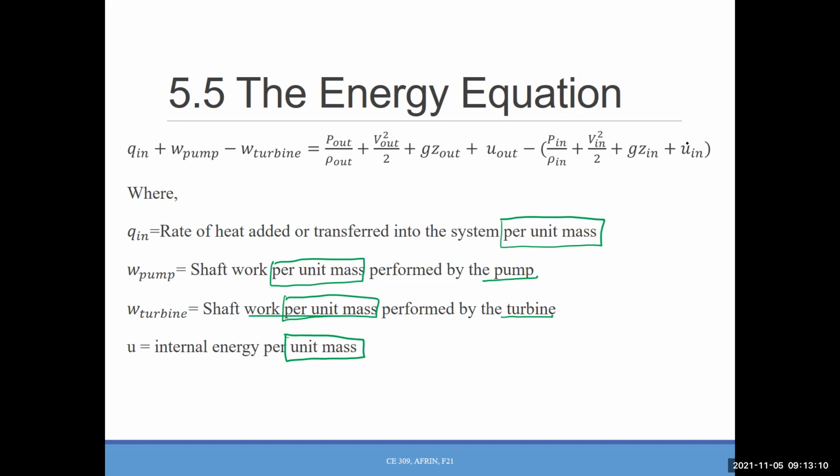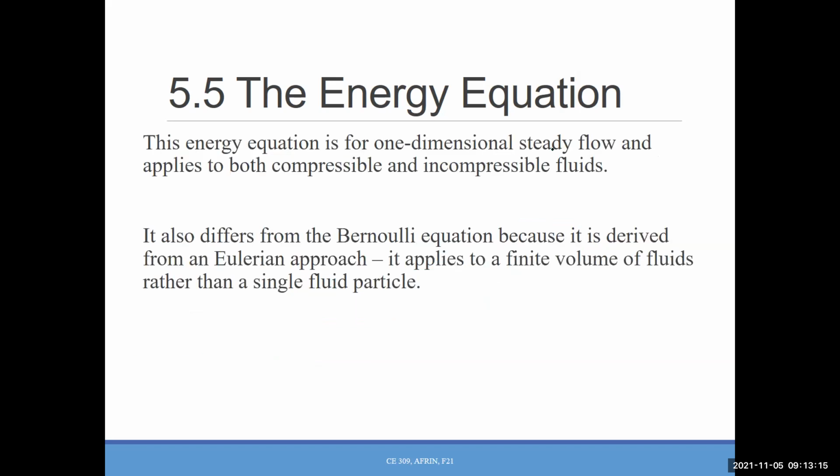So this equation is for one-dimensional steady flow, which is great because we are not doing anything unsteady in this course. And this equation applies to both compressible and incompressible fluids, which is great. This equation can overcome all the limitations we had in Bernoulli's equation.